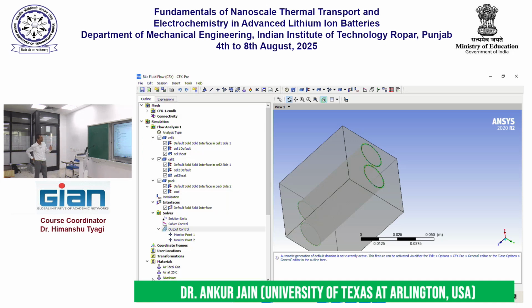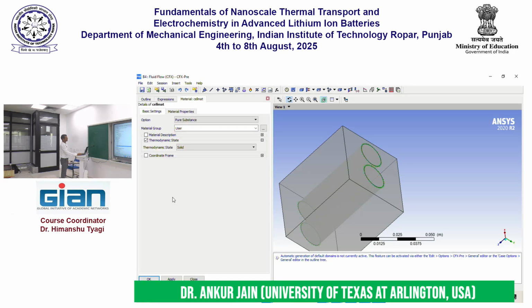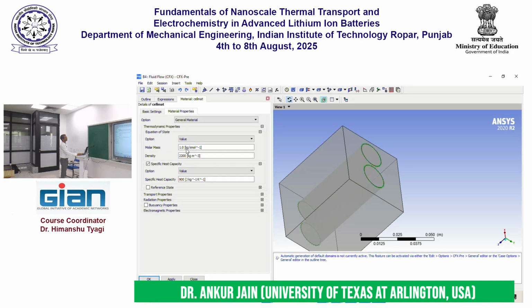Okay, let's take a deep breath and make sure that we have defined everything we needed. Initial temperature has been defined. I think life is okay. The cell material and the properties were defined here, cell mat. Using a blank material, and you are specifying my own numbers. As I was saying, there is an error here in the sense that for the cell material I'm specifying the thermal conductivity to be 0.5, whereas I know that it is anisotropic, right?